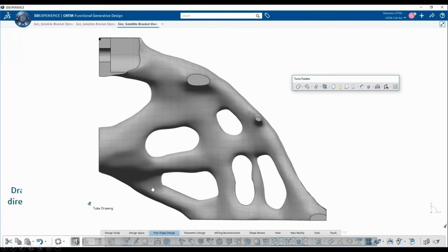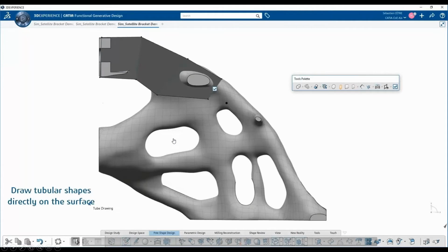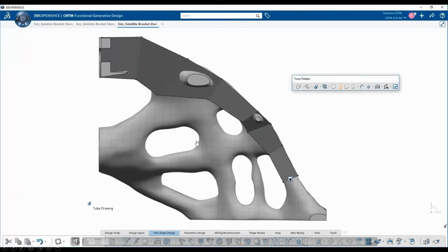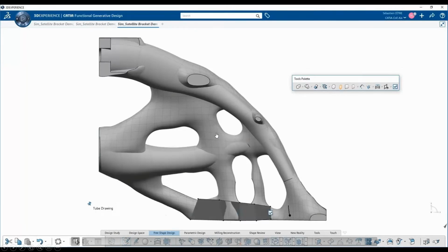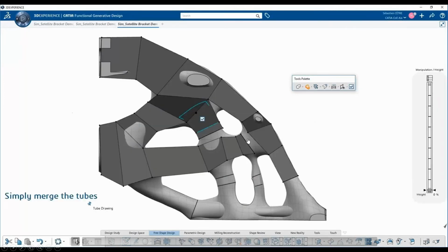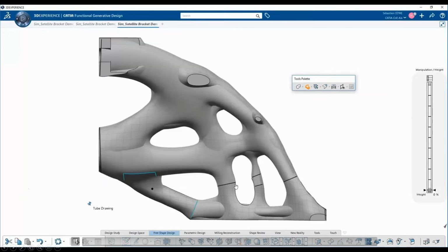So we use this imagine and shape methodology, where we draw these tubular structures over here, and we initially define a skeleton of it. Then, using the advanced join options, all you have to do is select each of these previously drawn cubes, and your geometry will be automatically created. All the joints will be automatically performed, as shown over here.